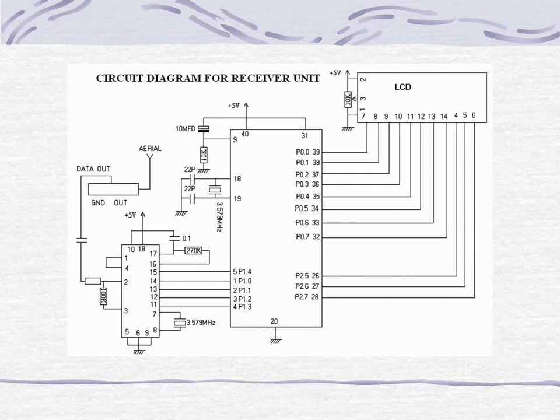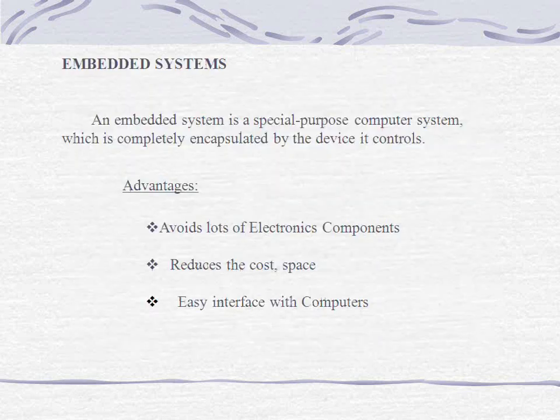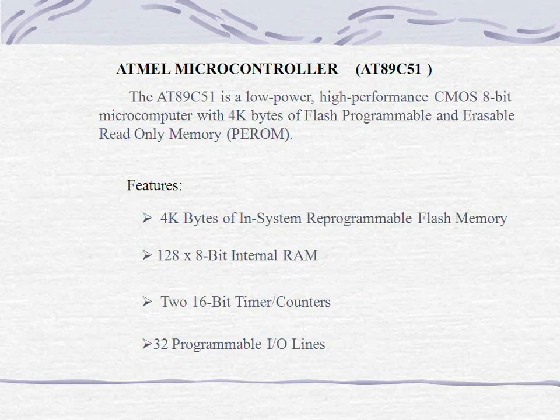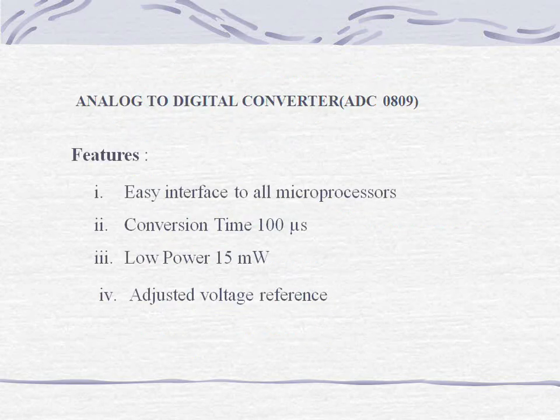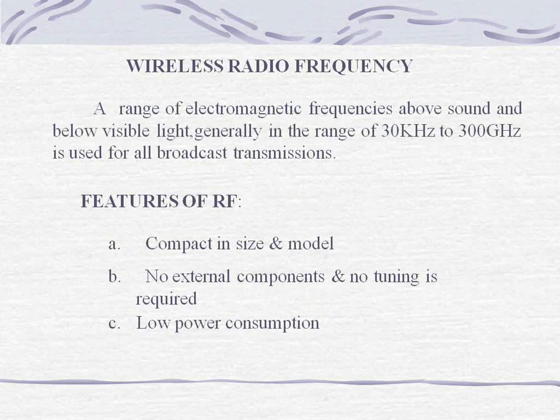The sample rate of this microcontroller is set by the program. The same working principle applies for the current measurement module. The only thing is that instead of the voltage sensor, here you have the current sensor. The current transformer is always short circuited, so you need a resistor.